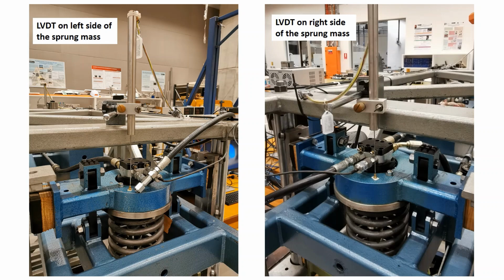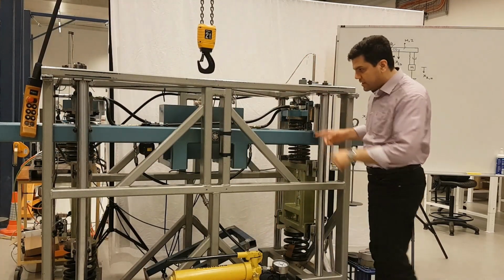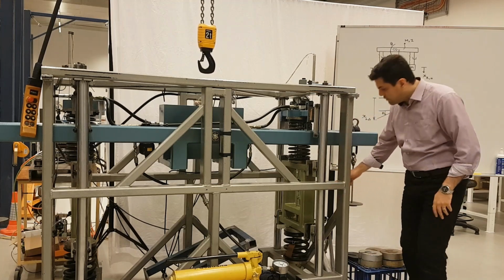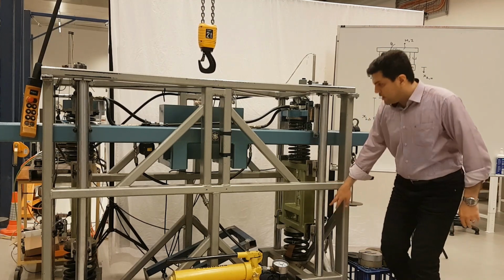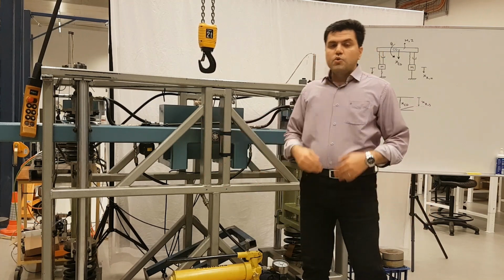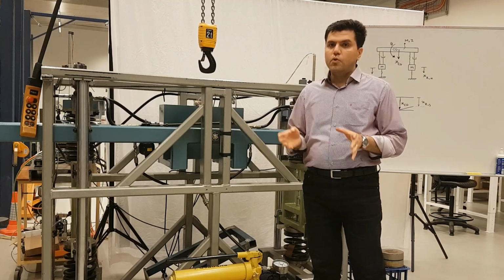Because an LVDT is a transformer, it requires an AC drive signal. A dedicated electronics package or signal conditioner is generally used to generate this drive signal, and also to convert the device's analog AC output to plus or minus 5 DC voltage. We also have another two LVDTs, maybe it's not visible in the video, but we do have another LVDT here, which measures the displacement of the spring mass on this side, and another one on the other side. So we measure the displacement or the vibration response of 4 points.